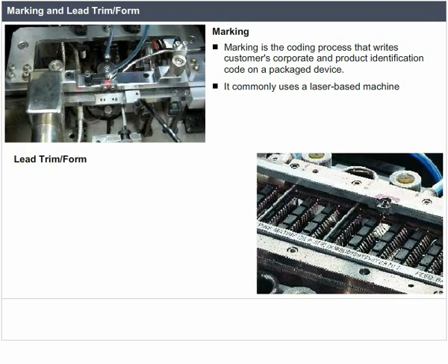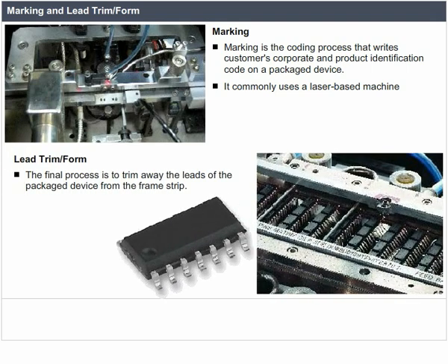Lead trim or form. The final process is to trim away the leads of the packaged device from the frame strip. The leads are cut and formed mechanically to the specified shape.